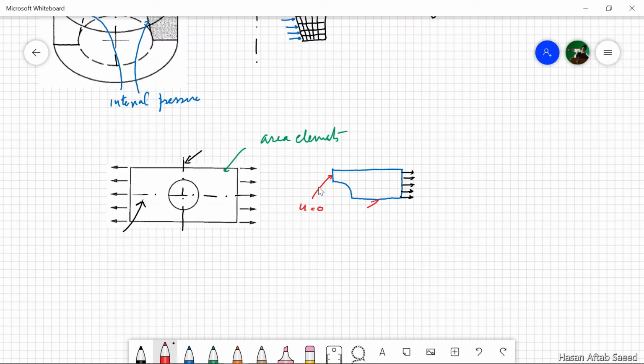When it comes to this line, no point on this line can either go up or go downwards. So here the v displacement is 0. As long as we do this, then we don't need to mesh the whole thing. All we need to do is something like this. Mesh this 1/4, and whatever number of elements you use, we will mesh this area also, but whatever the number of elements used ultimately, let's call it n. If you hadn't spotted this chance for utilizing symmetry, you would have needed 4 times n number of elements.